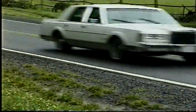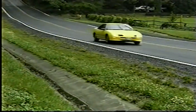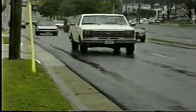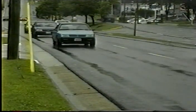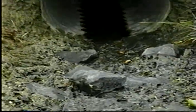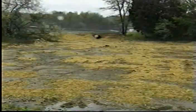Let's review what we have talked about in this film. Since water is the most significant cause of damage to the pavement structure, proper water drainage is important in maximizing the life of the roadway. Roadway design has been developed to keep water away from the pavement structure. This is usually done by providing a watertight surface, slopes to channel the water away from the pavement structure, ditches to collect the water, channels to carry the water from the ditches to a point of discharge, and underdrains to keep subsurface water from infiltrating into the pavement structure.